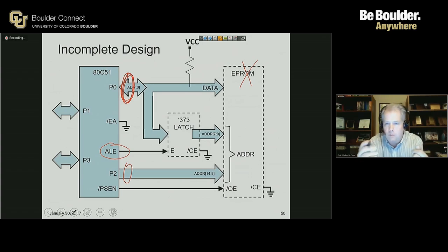So what can we do? I heard somebody mention if the P0 lines were low or high, then you wouldn't read this noise back in. What could we do to P0? We could tie a bunch of pull-up resistors to it, or maybe less than a bunch, just 1 or 2 strategically placed pull-up resistors, and make sure that whatever the processor reads back in does not decode to some instruction which writes to the PCON register.